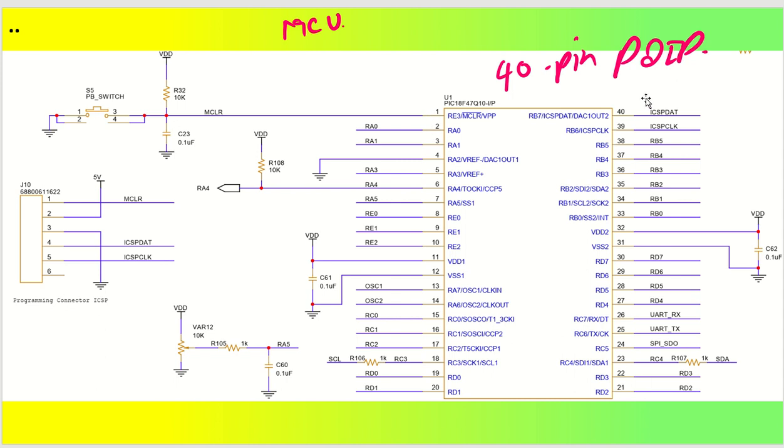Now, the very first thing that you have to proceed with for the microcontroller design, so that it doesn't get affected during your programming and working, is you have to connect your power supply. Let's say here it is VDD1 and VSS1, and this is VDD2 and VSS2. So you have to connect a bypass capacitor of 0.1 microfarad, that was recommended by the microcontroller data sheet.